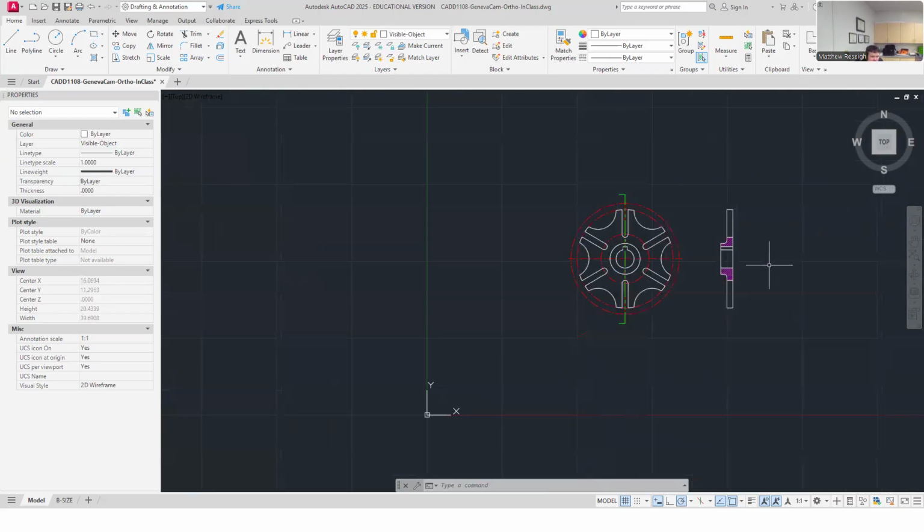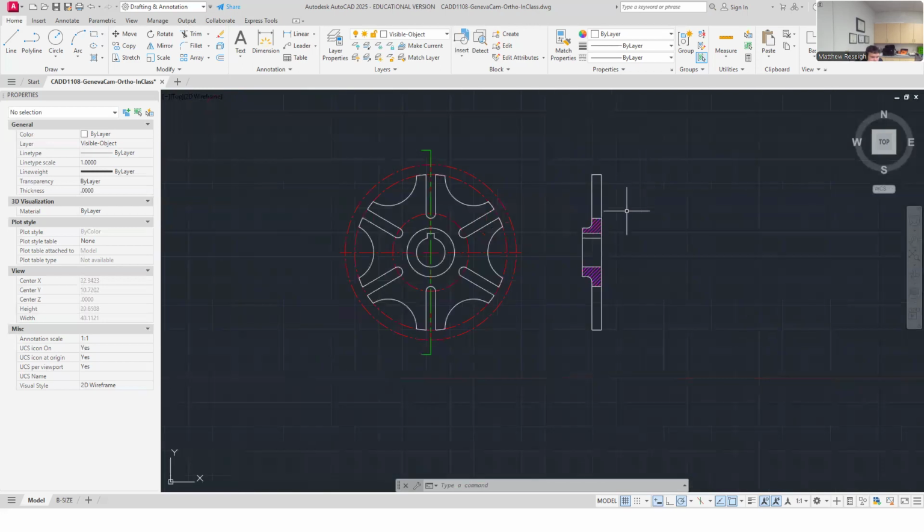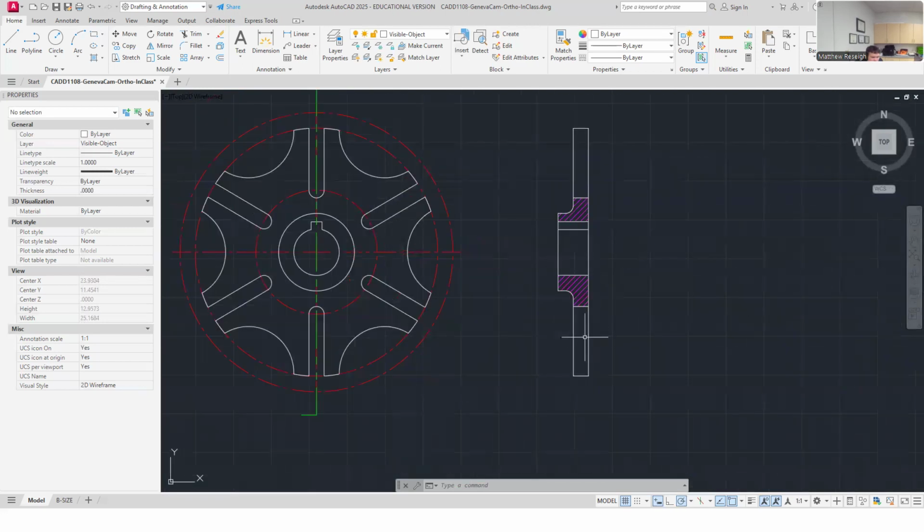I think this could be a little vague of which ones you need to add. And of course we've determined that we're going to eliminate any hidden lines. I know that I'm looking that way, and I would see all kinds of hidden lines from the points of these features projecting across over here. We're just going to omit them because they just add confusion, not clarity. And our section view is designed to clarify things, especially internally, not add more clutter. So let's just go with this, but I'm going to add the center lines there.